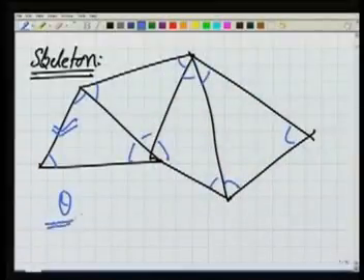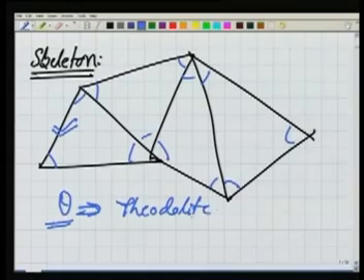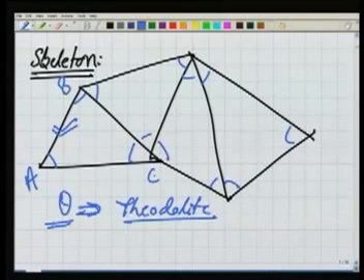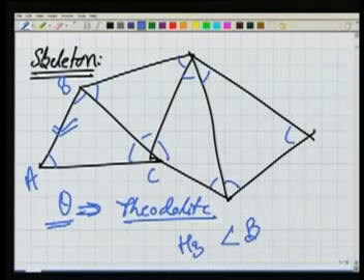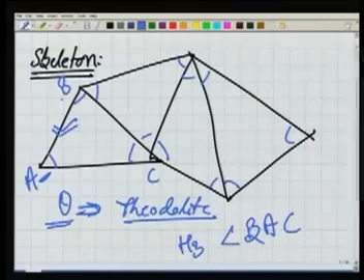Now the question is, how do we measure, number one, the angles? We know the method. We can use theodolite, and we also know how to measure the angles with the theodolite. We can measure the angles in horizontal plane as well as in vertical, because starting from point A to point B and C, I can measure the horizontal angle, that is B, A and C, as well as the vertical angle at A to B, because we can establish now the vertical control also with the help of these vertical angles.